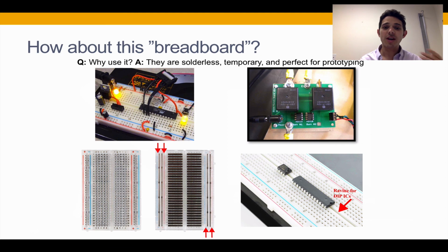So you want to use it when you want to prototype something because they're solderless. So it's easy to build a circuit super quick. However, because nothing's soldered, it's really not reliable. If you knock it over, then the wires might get disconnected. But it's really great for doing something temporary and quick. So it's great for prototyping. Let's take a moment to break down how the breadboard works.